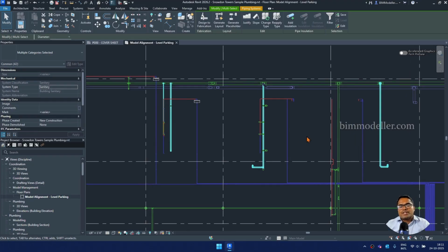So how do we differentiate it? In a rule-based filter, we must have a parameter so that we can define the rule. But for this, we don't have any parameter to define the zones. So we don't have any options. The same selection, we have to do it multiple times, or we may have to move it right, left, or for design purposes, multiple things are needed. So in that case, the selection filter will be much more useful.